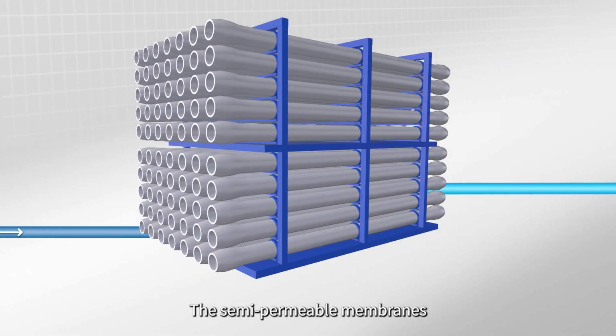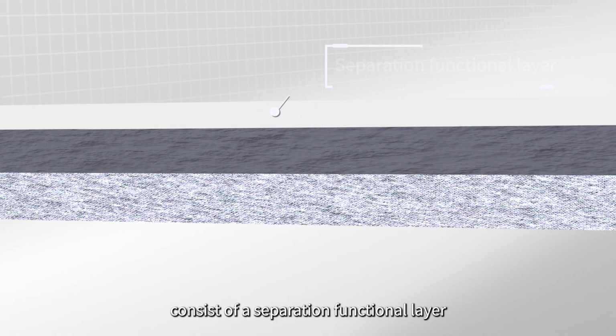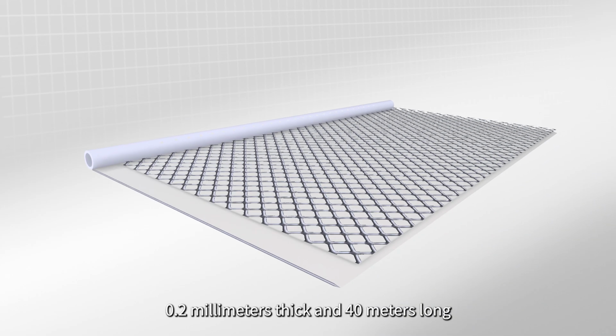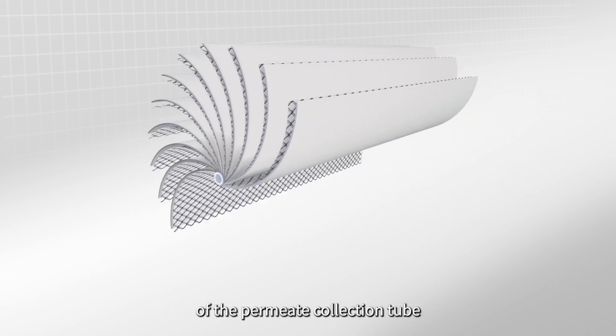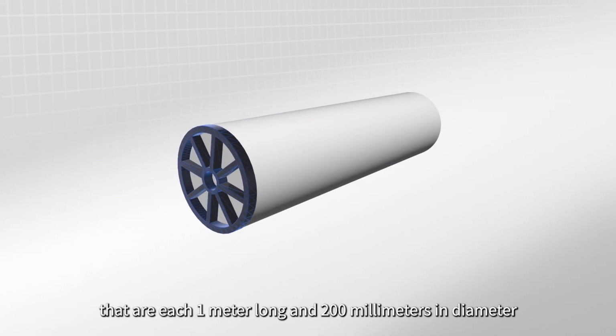The semi-permeable membranes used in the reverse osmosis facilities at the Tseung Kwan desalination plant consist of a separation functional layer, supporting membrane and substrate. Each semi-permeable membrane is approximately 0.2 millimeters thick and 40 meters long, which is spirally rolled around the outside of the permeate collection tube, forming reverse osmosis membrane modules that are each 1 meter long and 200 millimeters in diameter.